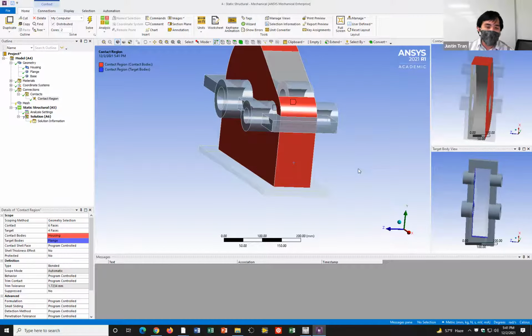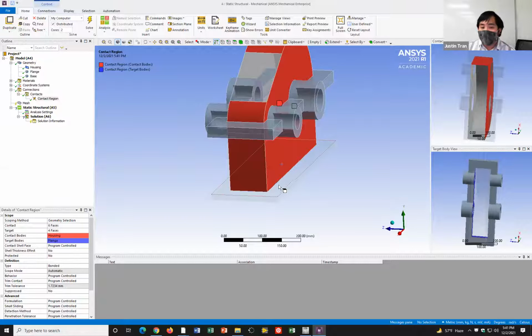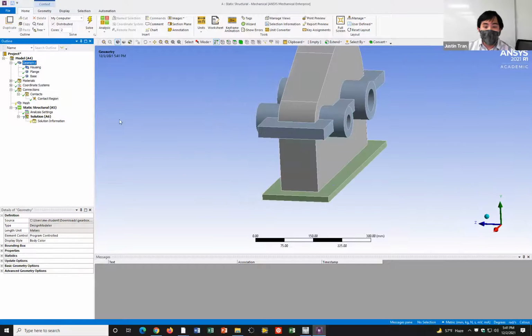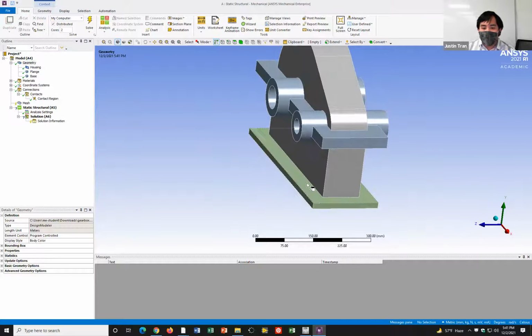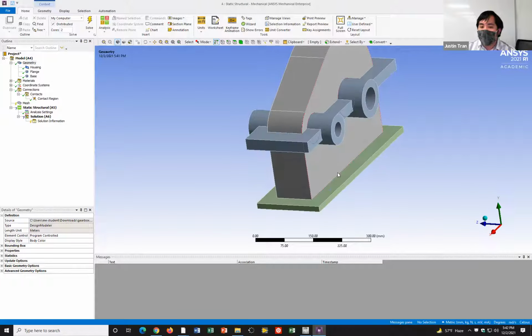So if you remember for activity 4, we had to make all the connections manually too, and that's because we have a connection between a shell and a surface. More specifically, it's because the edge of the shell is what's being connected to the base, and the edge of a shell is only just a line or an edge, so Ansys is not going to automatically generate connections between edges and surfaces. And so we're going to need to add this manually.